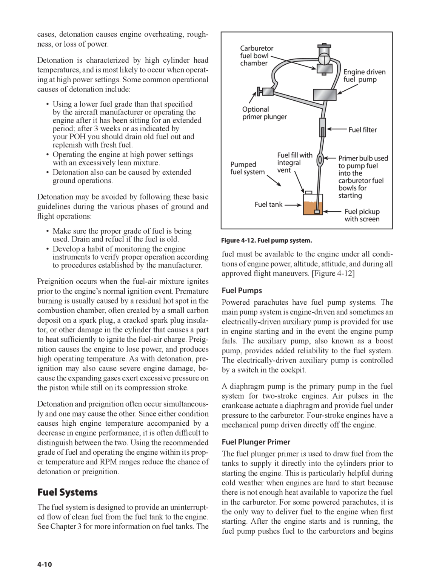Pre-ignition causes the engine to lose power, and produces high operating temperature. As with detonation, pre-ignition may also cause severe engine damage, because the expanding gases exert excessive pressure on the piston while still on its compression stroke.